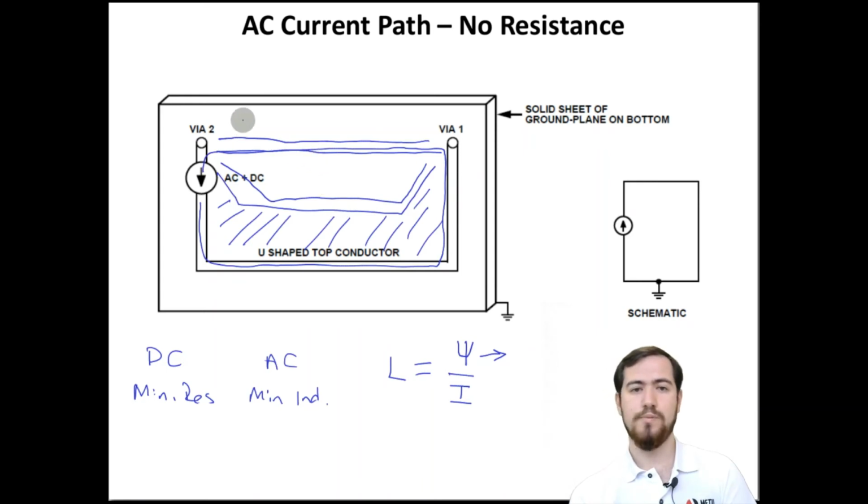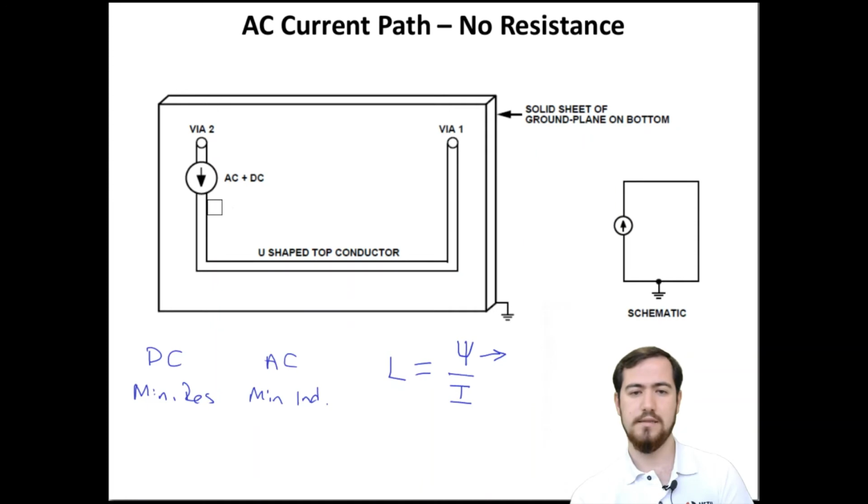The most optimum case, let's draw that one as well. The most optimum case for a PCB to reach minimized inductance is that the path should be put just below the top trace. What I need is to plot a bottom layer copper just under this top layer. Let me draw the current flow with red color on the top layer.